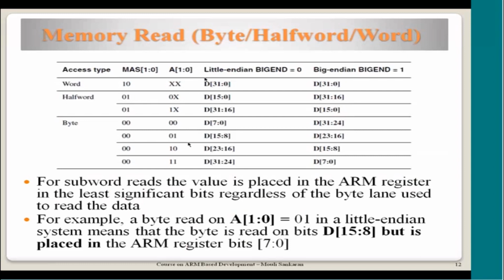Now you have to remember that based on little endian or big endian, this could be mapped to either the byte from the MSB, or the byte next to the LS byte. So what I am saying is, based on the endianness of the processor, the byte being read or written is taken from the respective data buses.